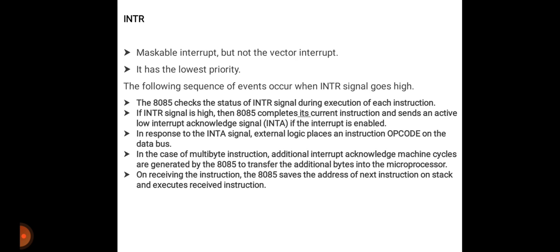Then, in response to the INTA signal, external logic places an instruction opcode on the data bus. In the case of a multi-byte instruction, additional interrupt acknowledge machine cycles are generated by the 8085 to transfer the additional bytes into the microprocessor. Then, on receiving the instruction, the 8085 saves the address of the next instruction on the stack and executes the received instruction. This is all about the INTR signal.